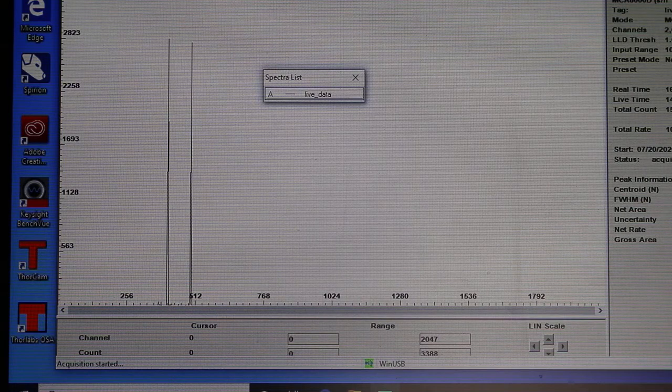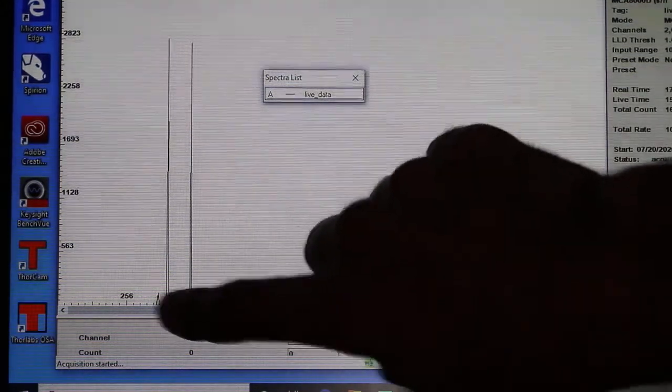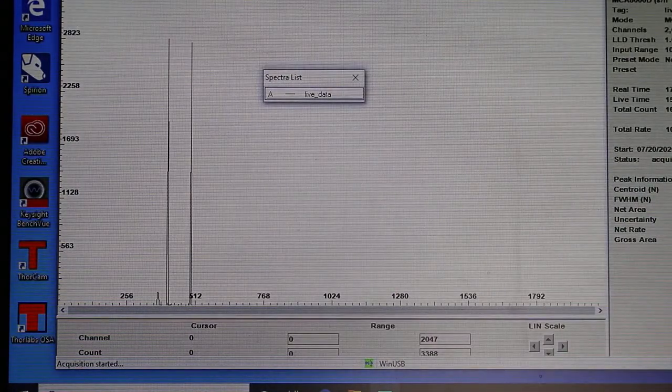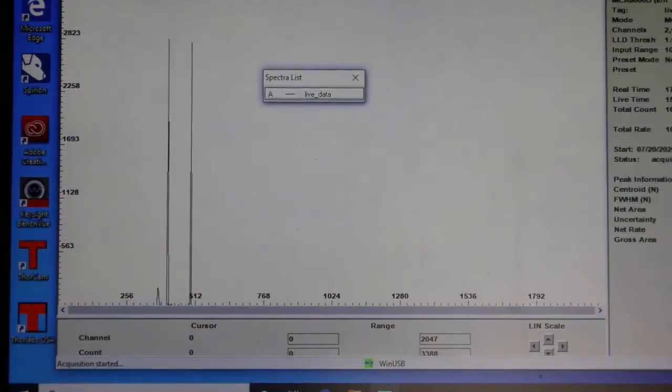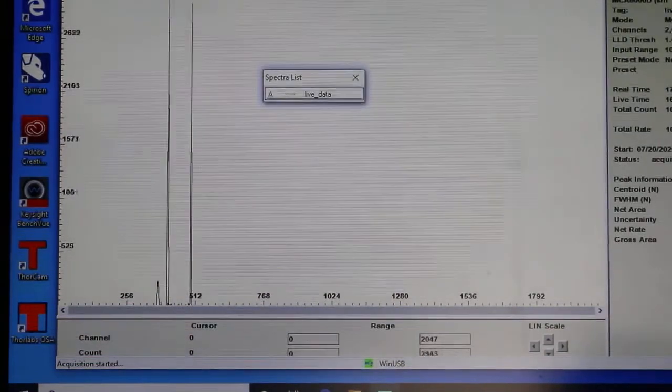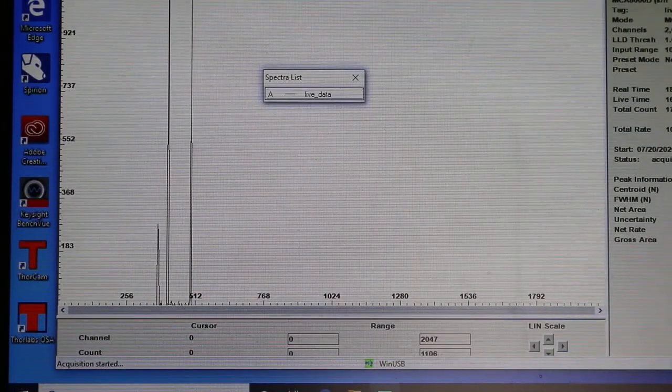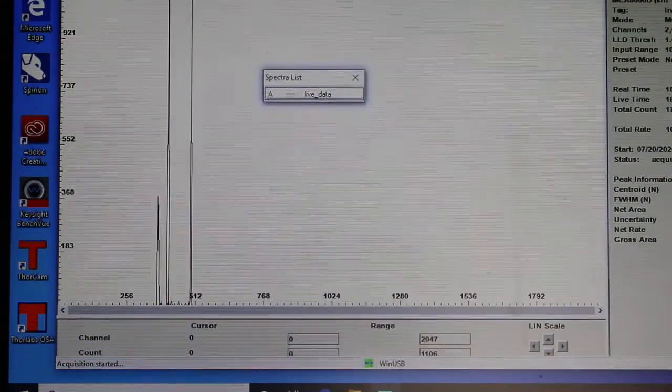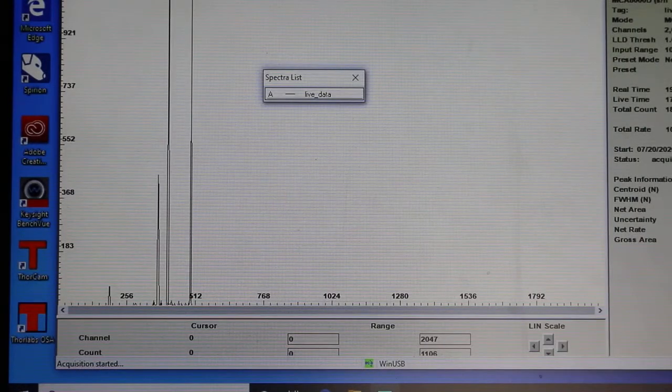See what happens if I go even lower in voltage. This is lower than both I've chosen before. I can see that little peak right there growing. That corresponds to that voltage. Maybe I'll let the other ones get off the screen so we see it grow a bit more. That one voltage has been seen almost 368 times now as the MCA samples it. And if I turn the amplitude down even more, I can stimulate another channel. There we go, something like that right there, see?